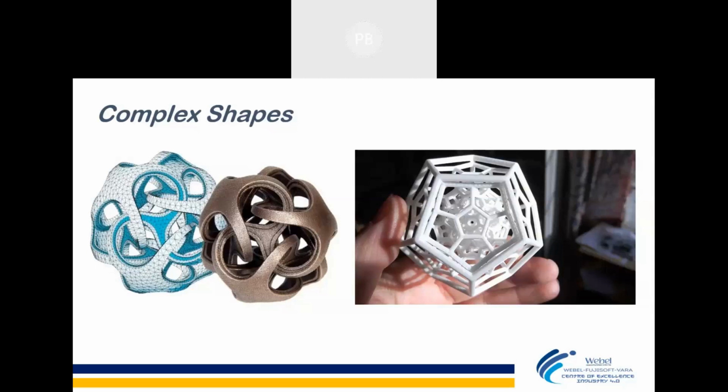As earlier there was a question, why would we use a 3D printer rather than conventional machines? Yes, if there is a complex geometry which is very difficult to do with conventional manufacturing, that is when 3D printing comes into play. But if you require a normal solid cube, you will not print it with a 3D printer, because 3D printing is not meant for that. It is meant for something which is not possible in the basic conventional way, for example a cube with a certain level of infill, or a cube with certain complex features. That can be done with a 3D printer.